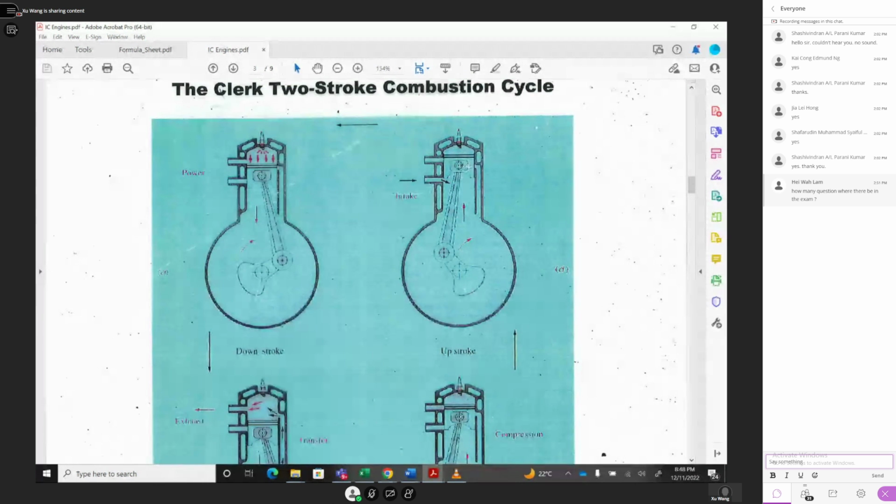Then go further, near the top center, and then you expose the inlet, and you find this air will be taken in. But when taken in, it will not go to combustion. It goes into the cylinder body, all the air inside. Okay, put the air inside, and after that go further up and get the minimal space, and then you have the injection.